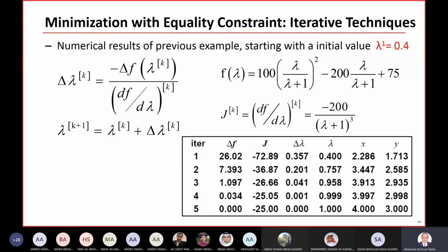When does Newton-Raphson fail, I mean when is there divergence? Maybe the first value is not the nearest to the right solution. If you compare Newton-Raphson with the Gauss-Seidel or Gauss method, Newton-Raphson is much better in terms of stability. Very quick, and also very efficient.